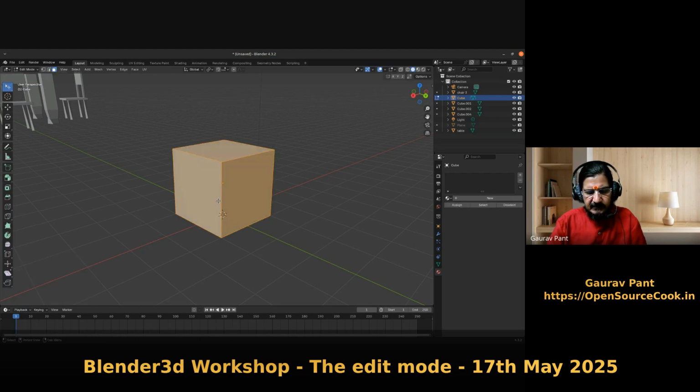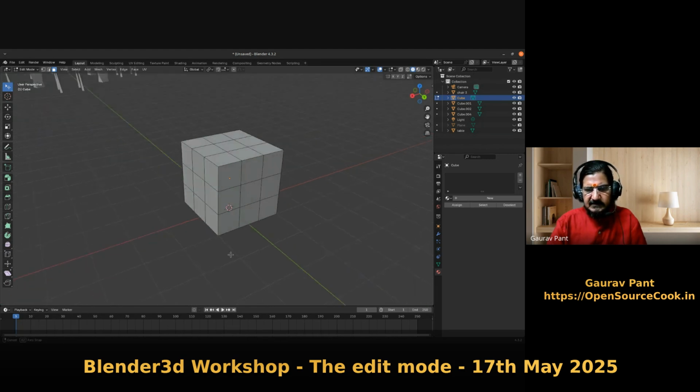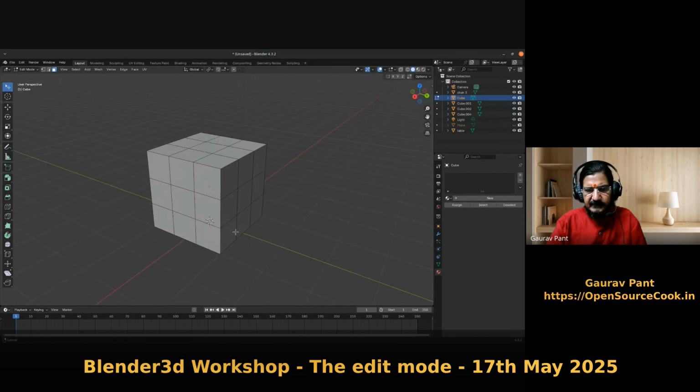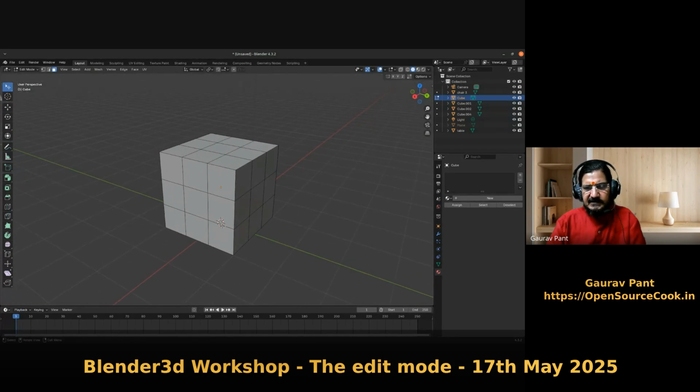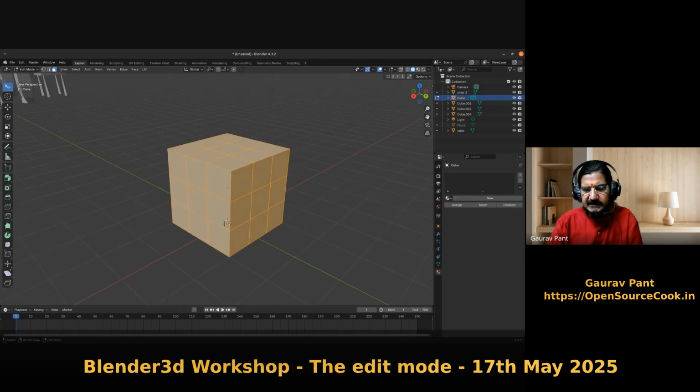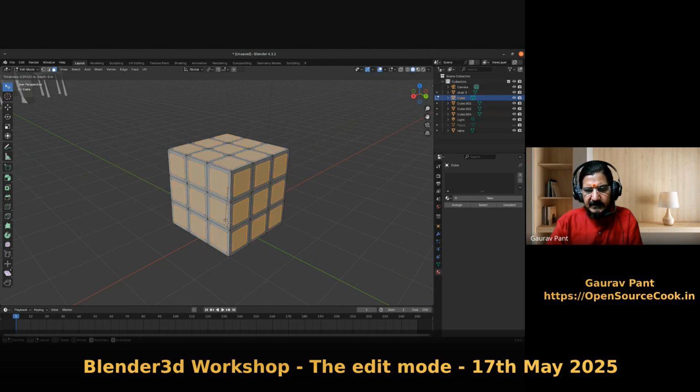So let's get back to our subdivide again. Let's reset it to the normal thing. You can reset by right clicking and choosing reset to default values, and this is our requirement. So this basic shape is ready. Now if you notice, the cube usually has some sticker or plastic piece which comes outside. So what we are going to do is select all the faces, make sure you are in the face mode, and press I 2 times, and now we will inset that.